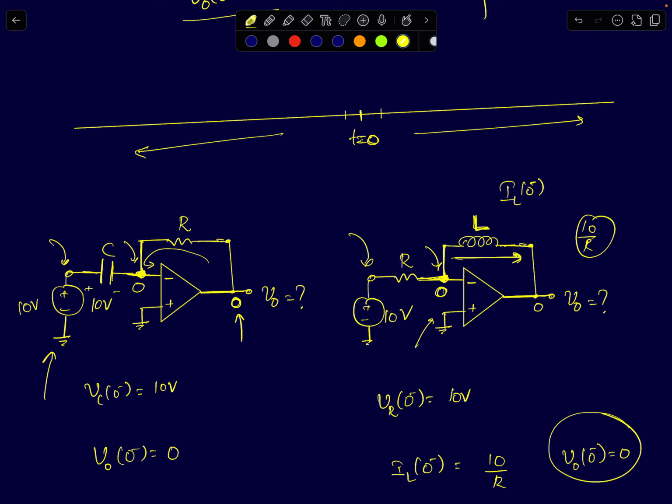So what you see here, even though I'm assuming the op amp to be ideal, all I'm trying to say is that for differentiator circuits, these circuits tend to have proper DC feedback in the steady state. Therefore, you can uniquely find out what the voltages and currents are in the circuit in the steady state.